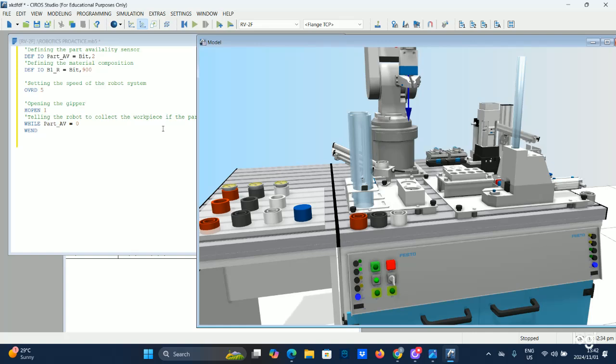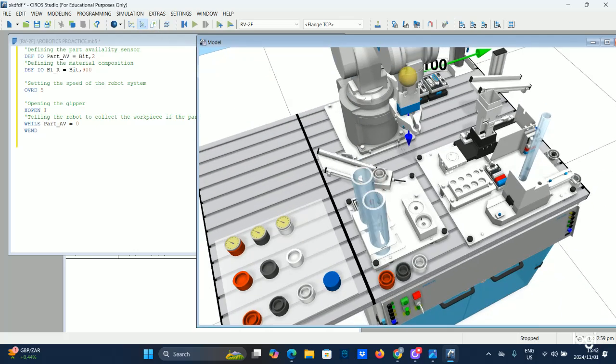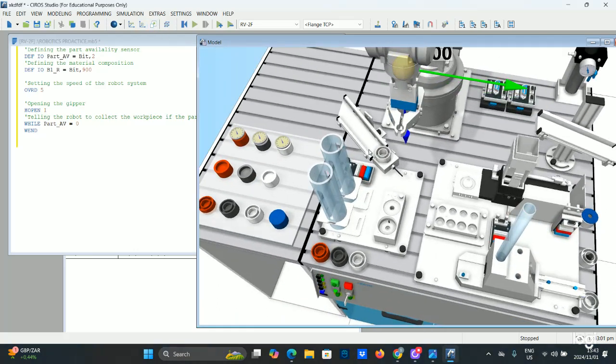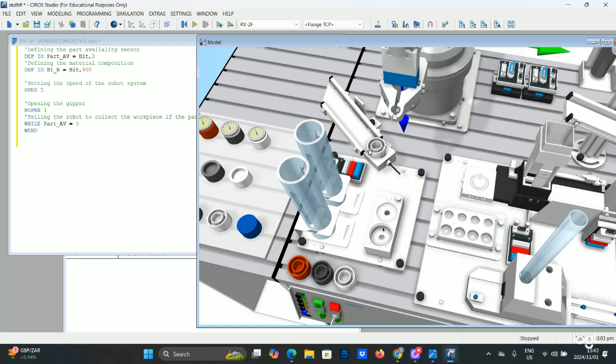You can't use MOV when you move your robot to a designated position. You first always have to use MVS before using MOV, because with MOV you risk collisions on the way to where you are going. You can use MOV if you are sure that there's gonna be no collisions along the path for the robot, but personally, I recommend you to use MVS.